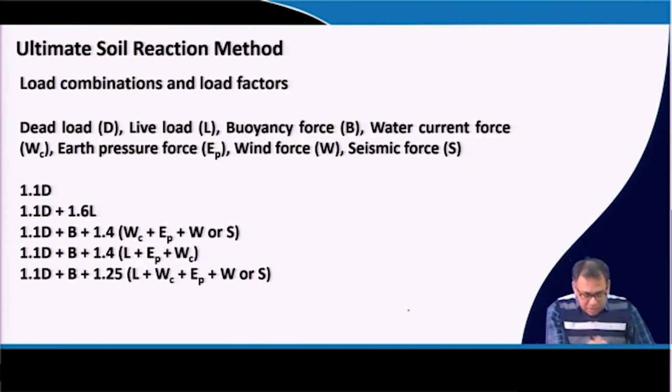Then the load combinations that we have to consider during the design or check are: dead load alone, dead load plus live load, dead load plus buoyancy load, then the water current, earth pressure, and wind load or seismic load. It is quite uncommon that the seismic force and the wind force will act at the same time, so that is why we take either wind load